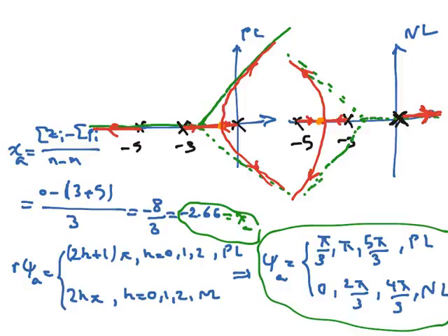In the case of positive locus, determining the points in which the branches cross the imaginary axis is important as well, because those points determine the values of KP, or rho, after which we will have instability. We can find the value for them using the amplitude criterion.